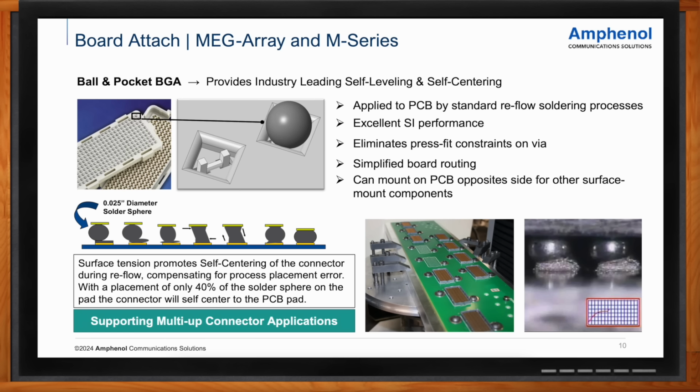And if you have a single connector on a PCB and you're bringing the mating half, if one of them's slightly askew, it's not as big an issue, because if there's no mechanical architecture, if there's no standoffs holding them apart, the board could adjust a little bit. But the moment you have two connector sets on a board or three connector sets on a board, if one of them would be off even microfractions of an inch, less than a millimeter, you'd have an issue, because now your contacts aren't aligned, your housing's not aligned, you're going to have mechanical interference, you're potentially going to damage a pin. And we don't see that with these connectors, which is just really great.